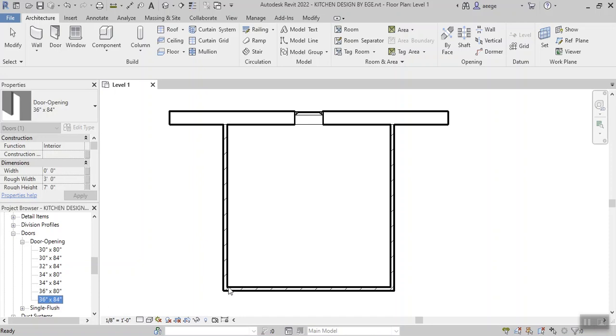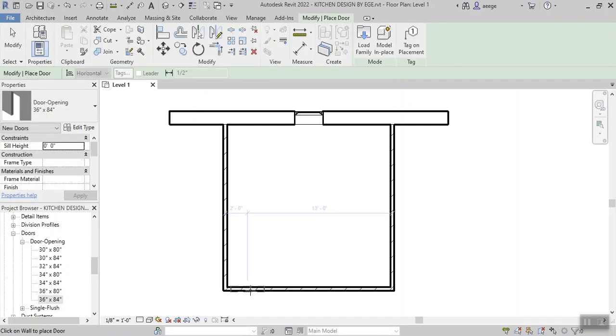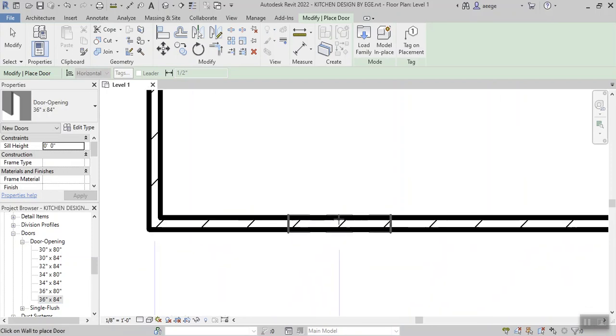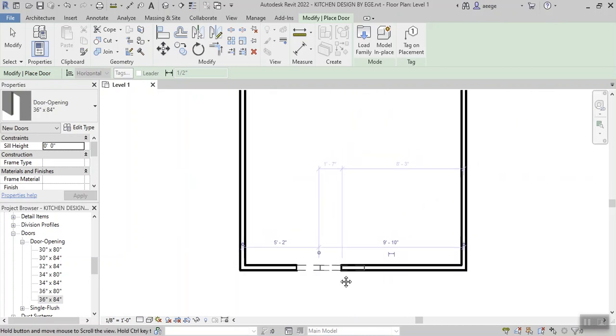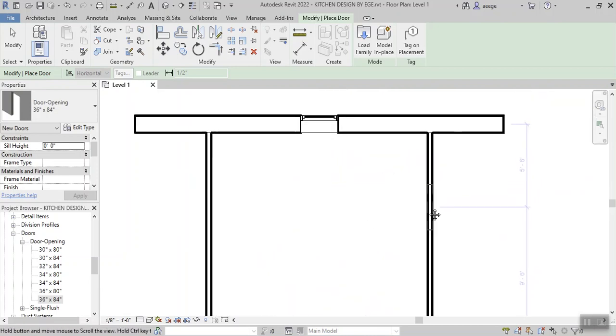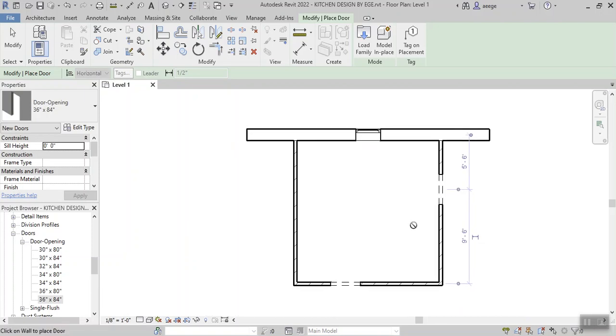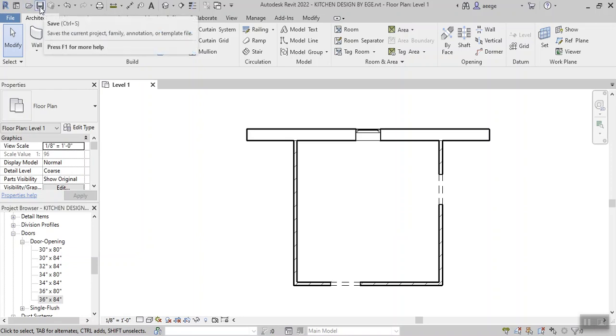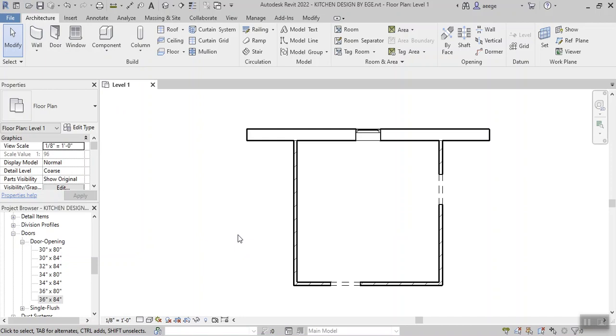So I can literally take this, drag it here, and bring it onto the wall. As you can see, I am hoping that you can see this. Like that, click. And move your cursor over the other wall and click again. Now we have two doorless openings. Escape. Again, every time you accomplish something, go save, on the top left corner. What else do we need?